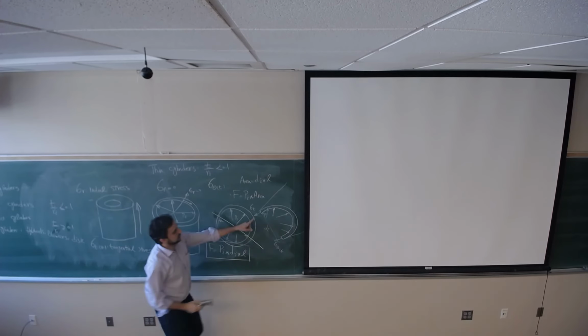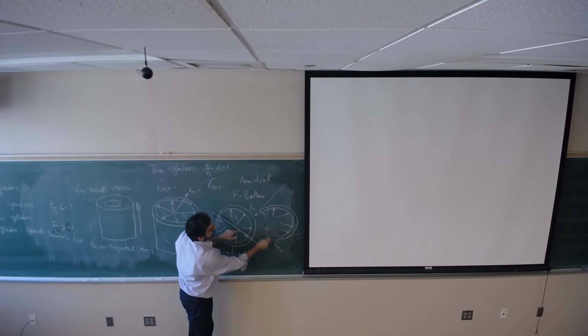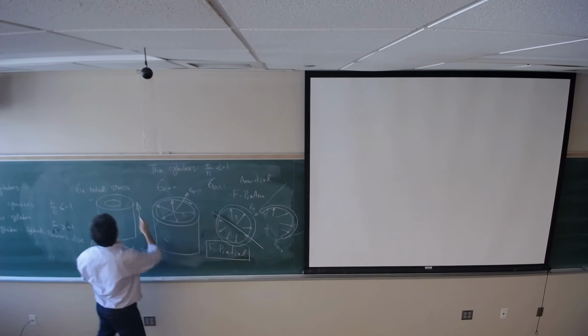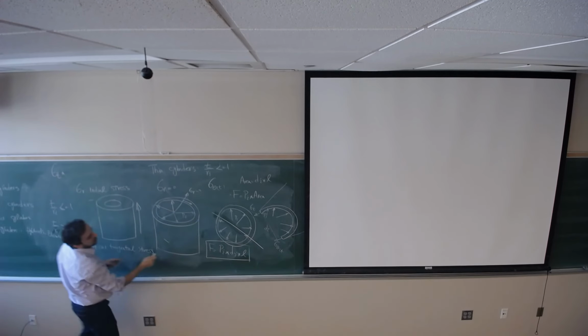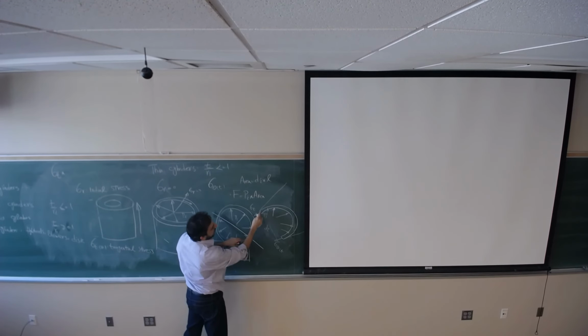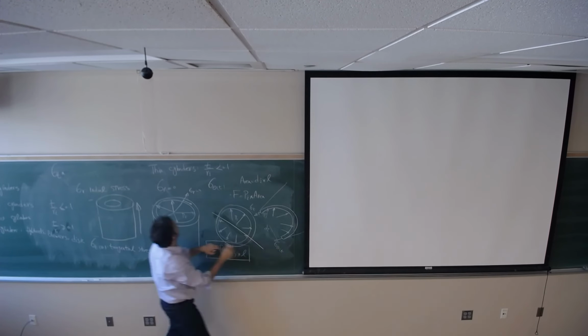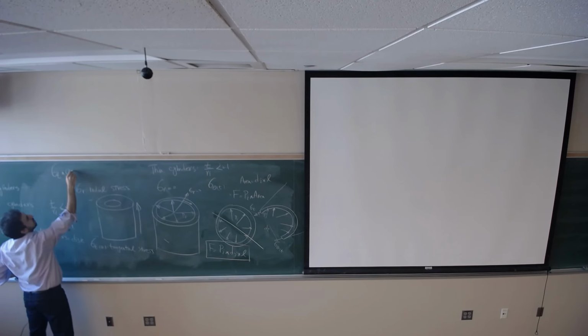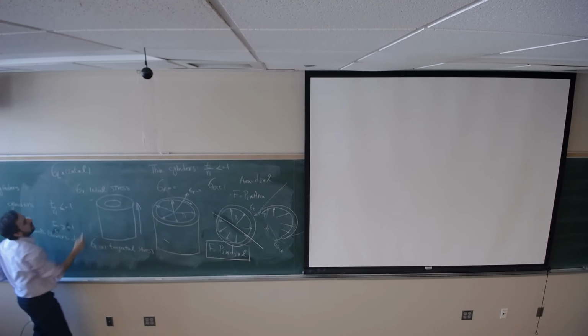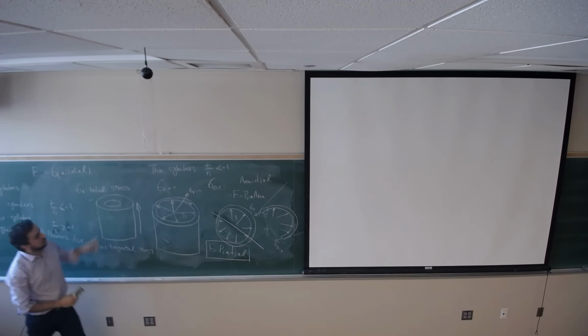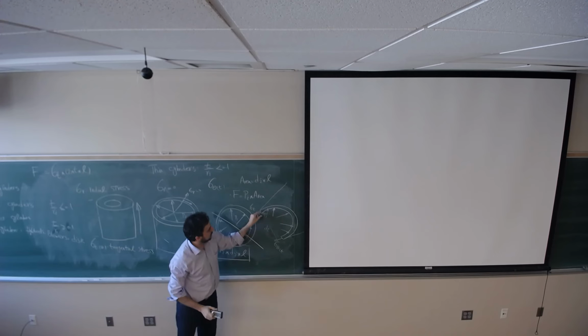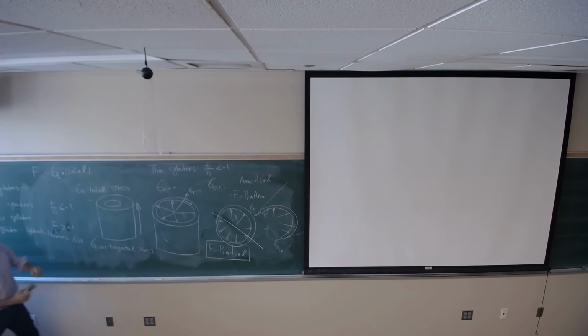So this force is supported by these two stresses. So sigma T times this area. The area is the thickness T times L, and I have two of them, 2 times T times L. So sigma T times 2T times L is going to be the force coming from the internal stress.